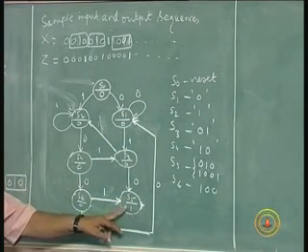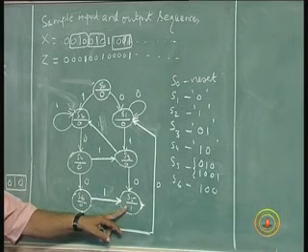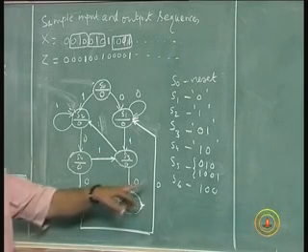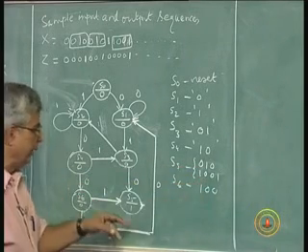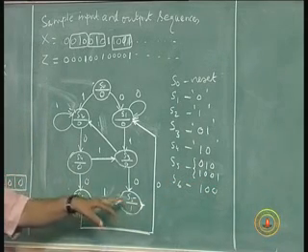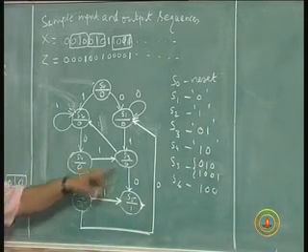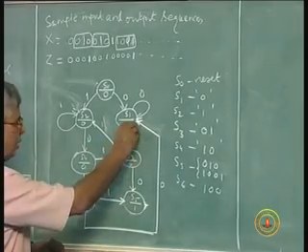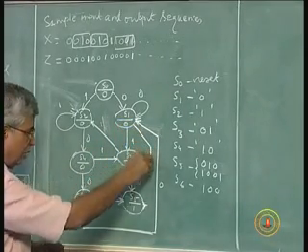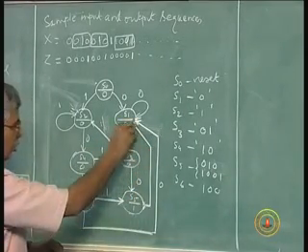S5 is a state where an output is 1. That means we have completed a sequence, either 0 1 0 or 1 0 0 1. Whether a 0 or 1 occurs, it should only be a start of a new sequence. If a 0 occurs, it will go to this S1, because that is the start of a new sequence with a 0 for 0 1 0.